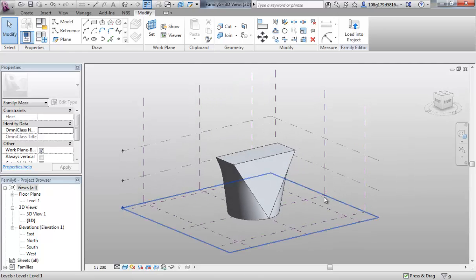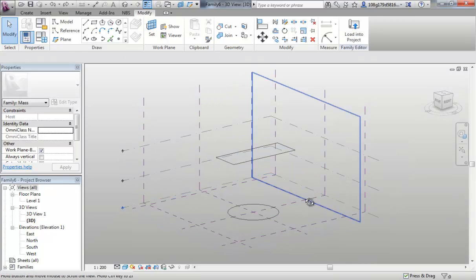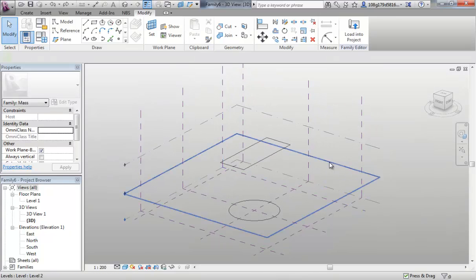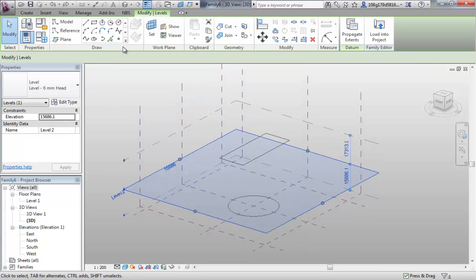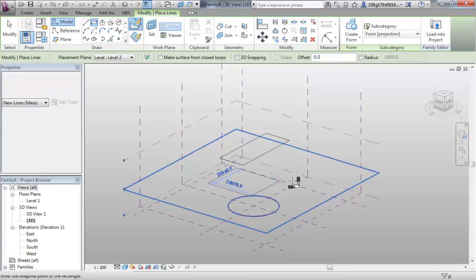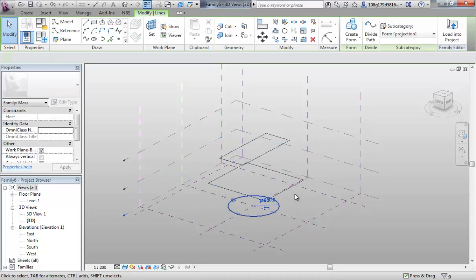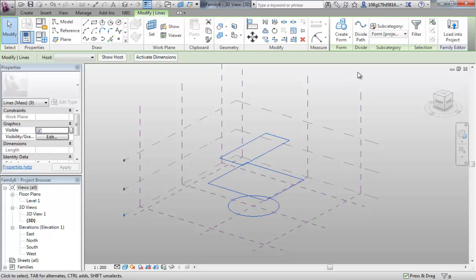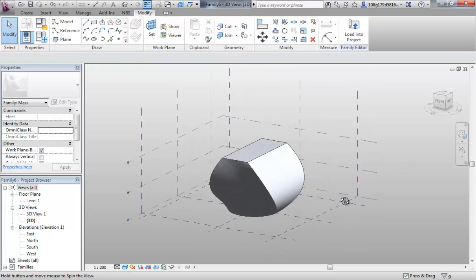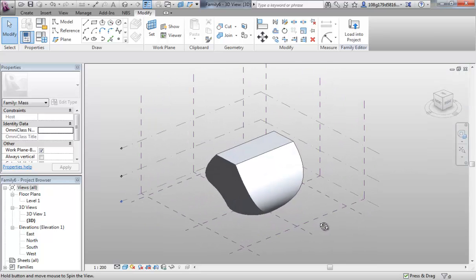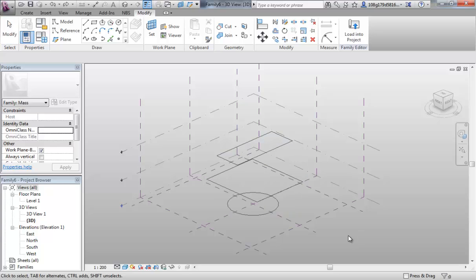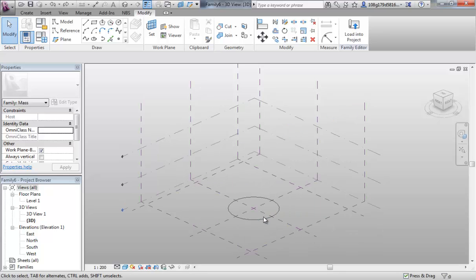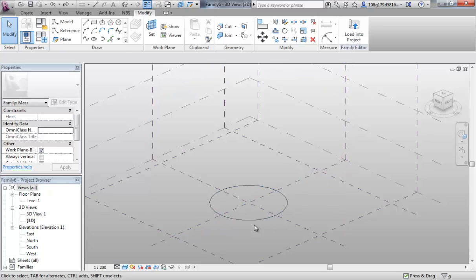Okay, it's very simple. If I undo that last Create Form move and select my central one, I can add a further form into here. This time press and hold my control to add all 3 to the selection, and you'll see that it creates a shape interpolating through the 3 profiles. Okay, I'm going to completely undo that process and leave myself with the one centralized shape that I drew on the floor.